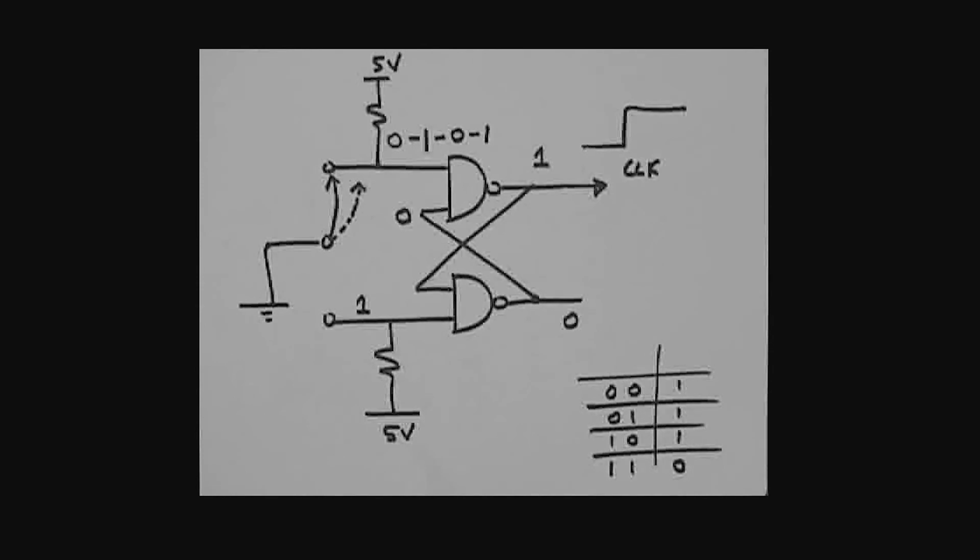Next time we're going to look at what some of the problems are with this traffic light system. One of the problems, I think, is that crossing switch. You're going to keep it pressed basically until you actually change states. If you just tap it momentarily, it may or may not change states. The other issue is that the machine so far only allows one state time for the people to cross the road. Think about that. That's not a good situation.